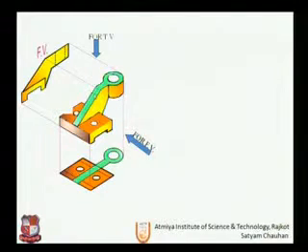So here this rib section is visible. Mostly in mechanical objects, the rib is always drawn inclined, hence it's visible in two views. We will see later in this session what the rib is and why it is required.